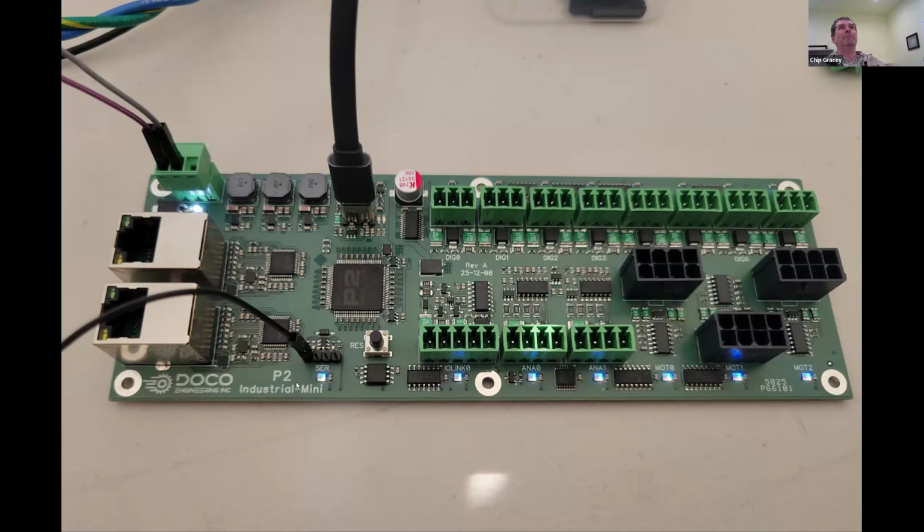Turns out he was a big believer in the P2. A while back, he checked out like half a dozen sites with the name P2 in it. He owns these URLs, or the site names anyway. So this is a board I designed for him. This happened really quickly and took a lot of hours, but it was about 6 weeks from concept to this finished circuit board. I had to learn a lot about 24 volt IO that PLCs use, and how to harden it to protect against a possible miswiring or a possible ESD event or something like this.